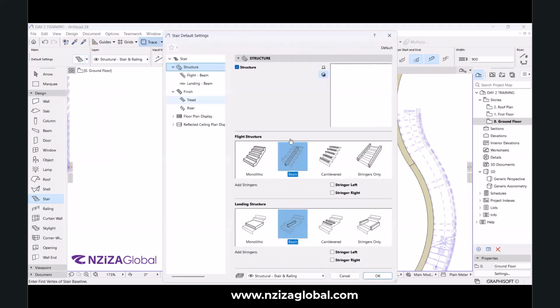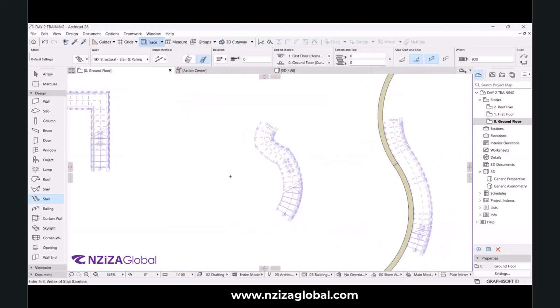Let's go to number two. Second way. I'll click OK. Then I'll click where to start, like creating the stair that I just showed you in the pictures. I'll click here. And you see, there are a number of things. Let's select this one, Arc by dot.